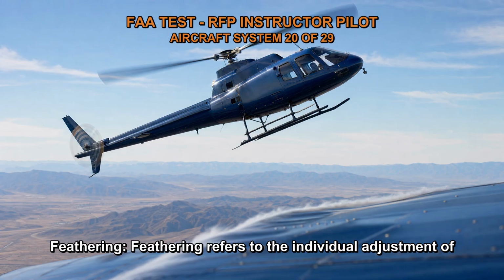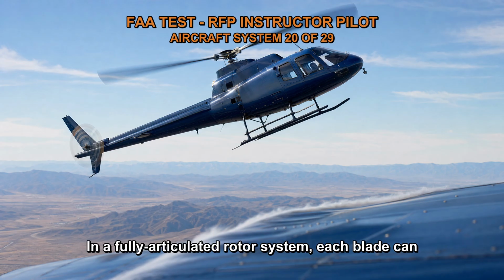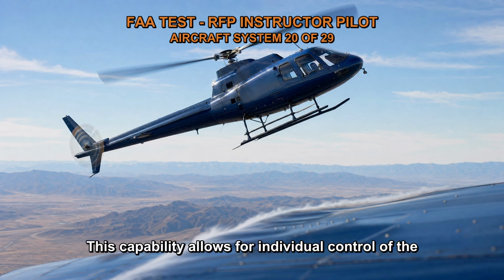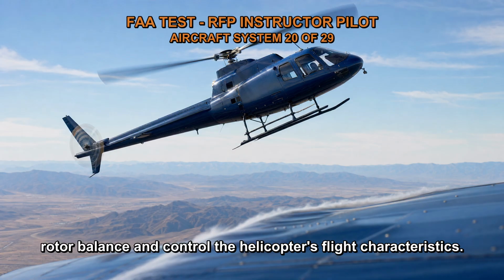Feathering. Feathering refers to the individual adjustment of the pitch angle of each rotor blade. In a fully articulated rotor system, each blade can be feathered independently. This capability allows for individual control of the lift produced by each blade, helping to maintain rotor balance and control the helicopter's flight characteristics.